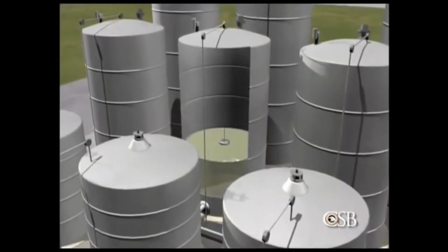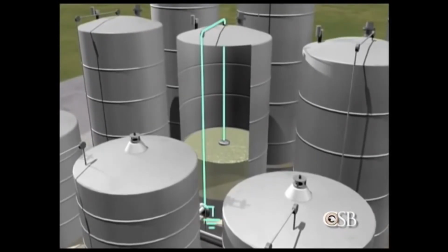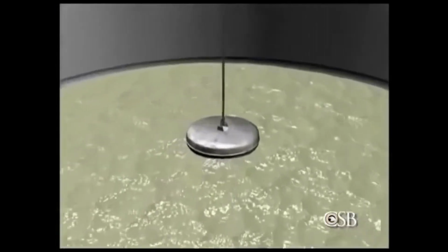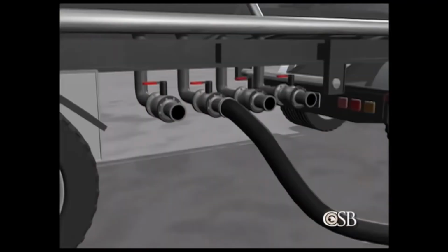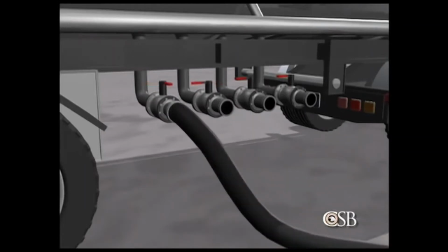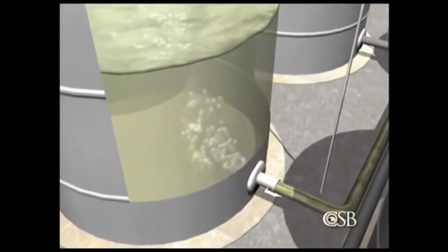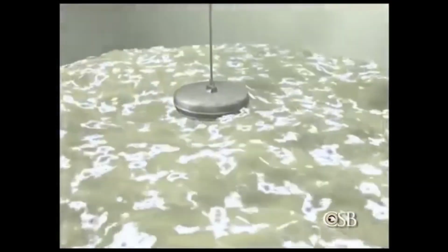Inside the 15,000-gallon storage tank, there was a device for measuring the liquid level. A metal tape, which was grounded, was suspended from pulleys and connected to a metal float by a loose, flexible linkage assembly. This linkage presented a hidden danger during the filling of the tank. The solvent was pumped from 3 tanker trailer compartments into the tank. As the hose was switched from one compartment to another, air entered the line, creating bubbles and turbulence inside the tank. A static electrical charge built up in the non-conductive liquid.